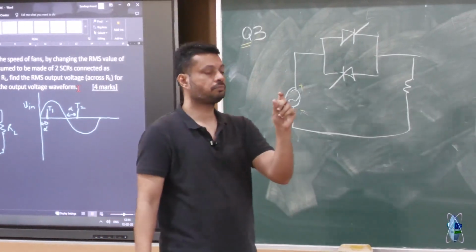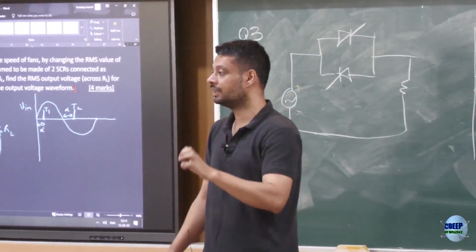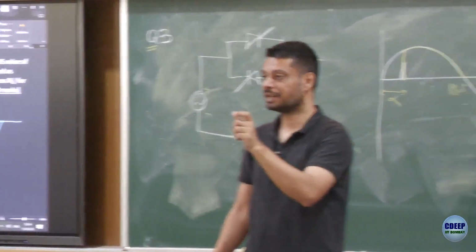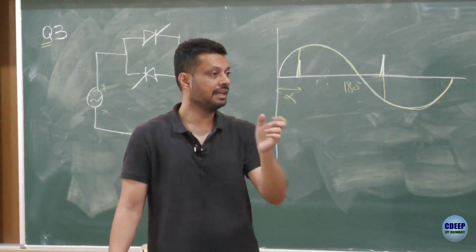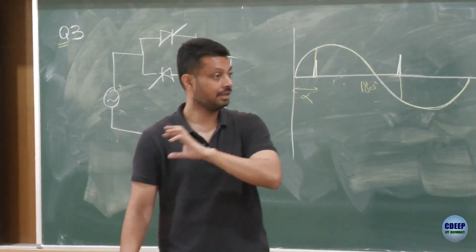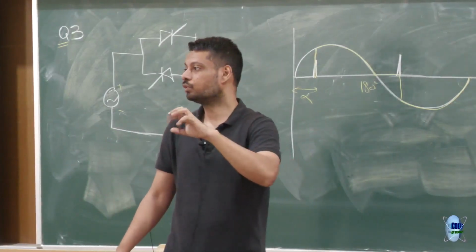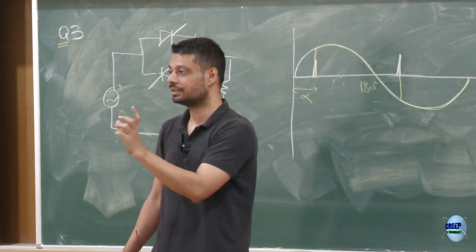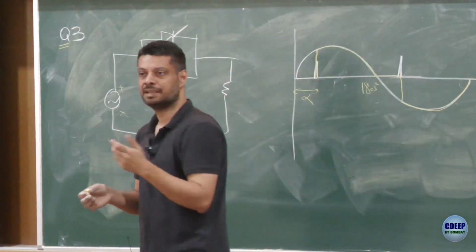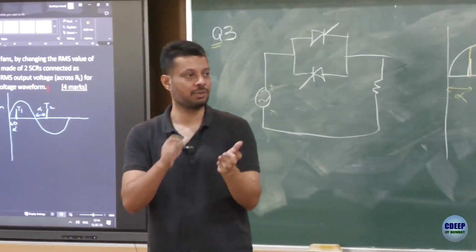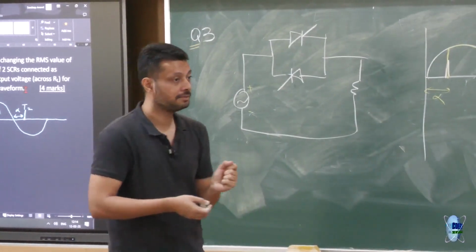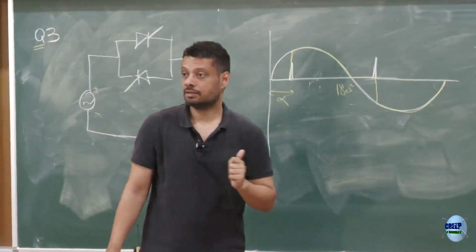Those speed regulators where you can do a continuous speed control, you have seen, some regulators have notches 1, 2, 3, 4, 5 and some have this continuous control. Those which have continuous control would have this kind of thing in it. Those which have notches would most likely have the capacitor switching network in it. You can just open them. The capacitor one is very obvious. Once you open it, you will see 2, 3, 5 capacitors connected in that block. Is that okay? Any question?